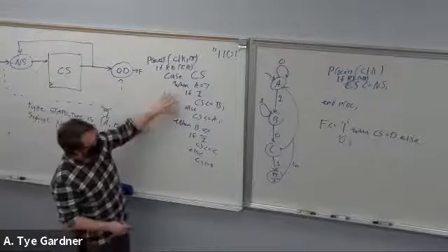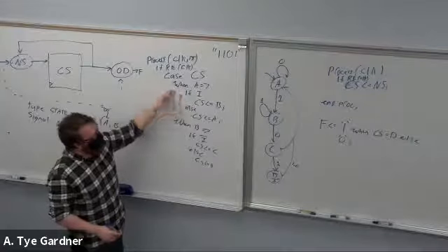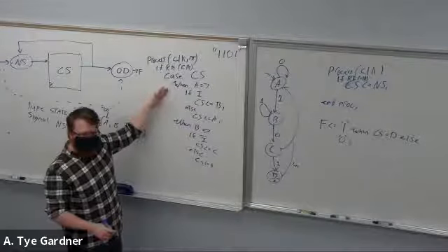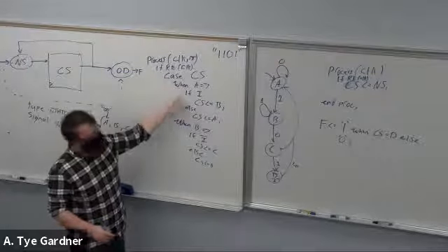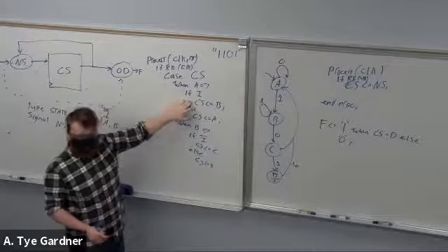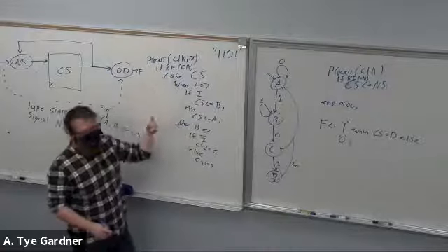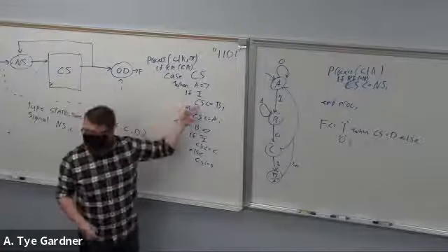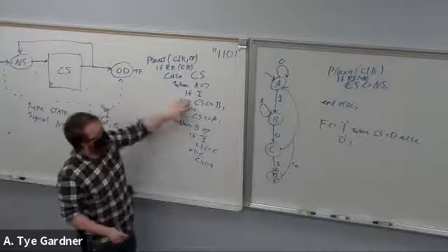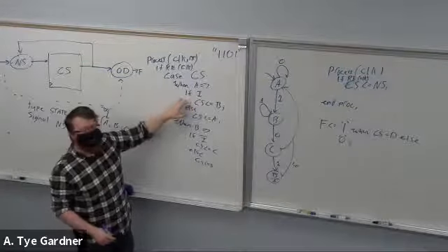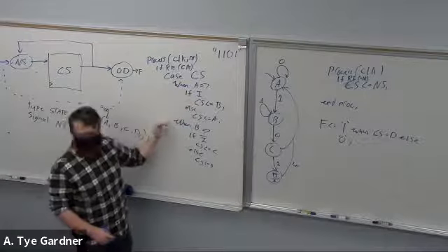Now, I'm in state A, a rising edge of a clock happens. And it says, oh, I'm in A, I is true, let's change current state to B. But since current state isn't in this process list and I need the rising edge, current state has updated, but I'm not there yet, right? So current state updates to B, but on the next rising edge of the clock, I'm in this case statement.